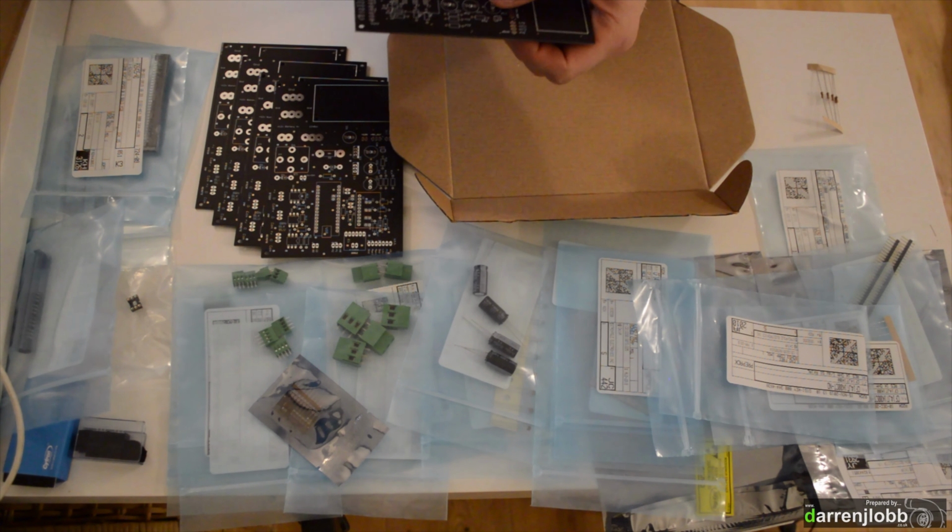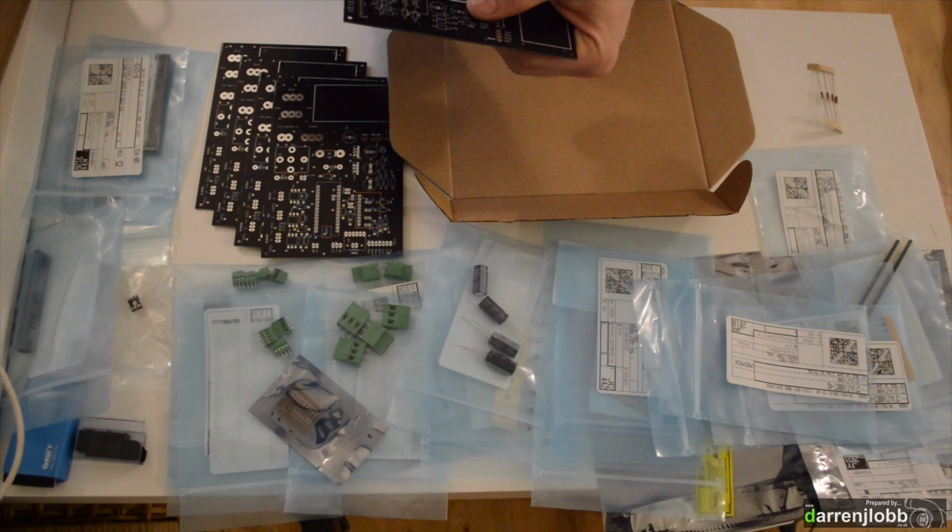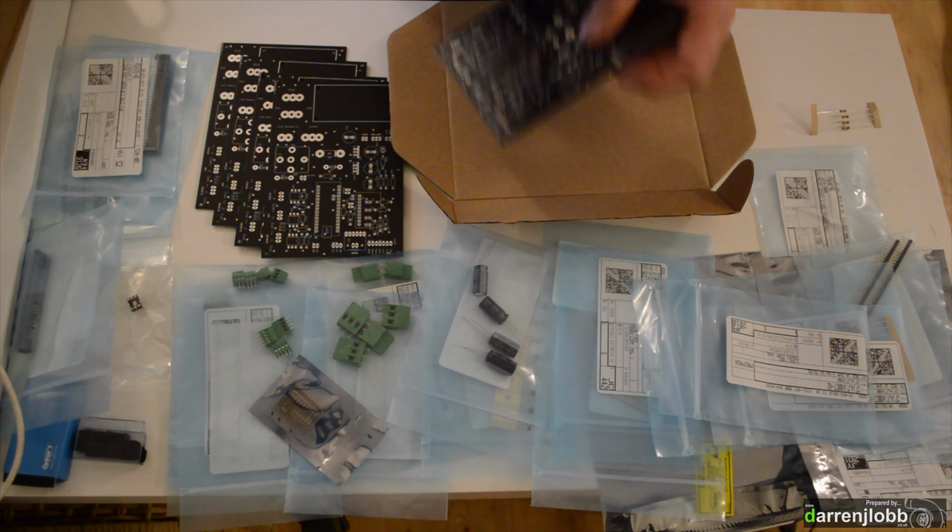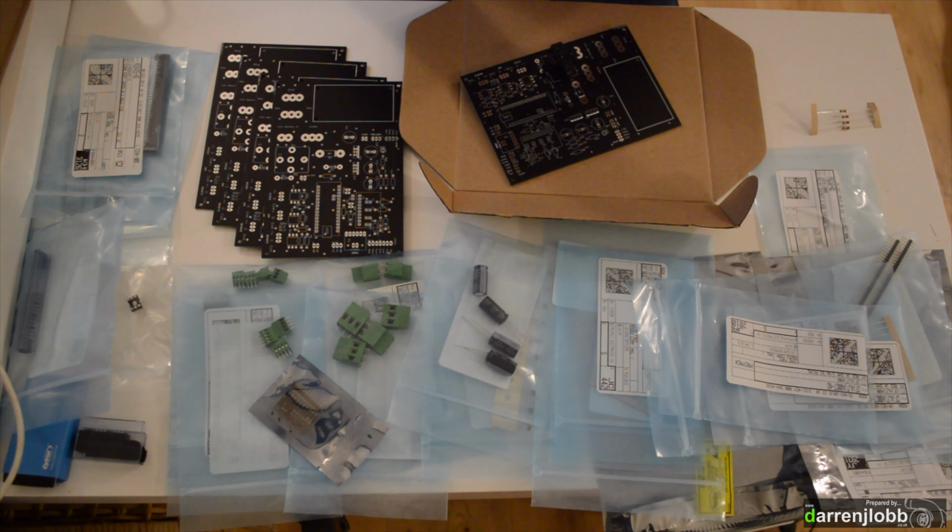So just putting some resistors on the board now. We find anywhere where it says R as a resistor, so R19, you look on the parts list, that is a 1K resistor. We've just got one out of the box now, they normally come in little strips like that. One thing to note with resistors, they're not polarity influenced. It doesn't make any difference which way around you put it. So we want to just bend the terminals down and slide it through the board, so it's flush with the top of the PCB.